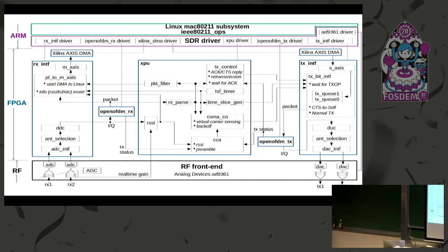In the center is all the CSMA low MAC layer in the FPGA. You need lots of functionality. You can check the standards; they define everything very clearly. You need CCA, to detect whether the channel is busy or not. Two methods: one based on RSSI, which has to be precise, otherwise you get the wrong answer; and one based on preamble, which comes from the OFDM receiver status. You output the channel status to the CSMA/CA engine. In this engine, you do the random backoff according to your contention window, etc., all the parameters in the standard.